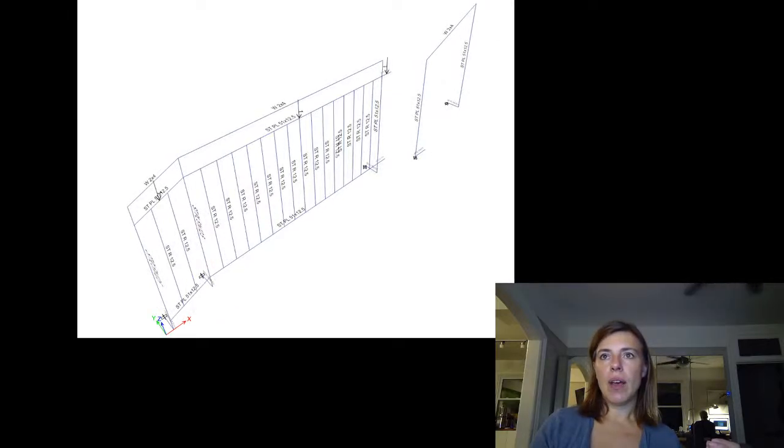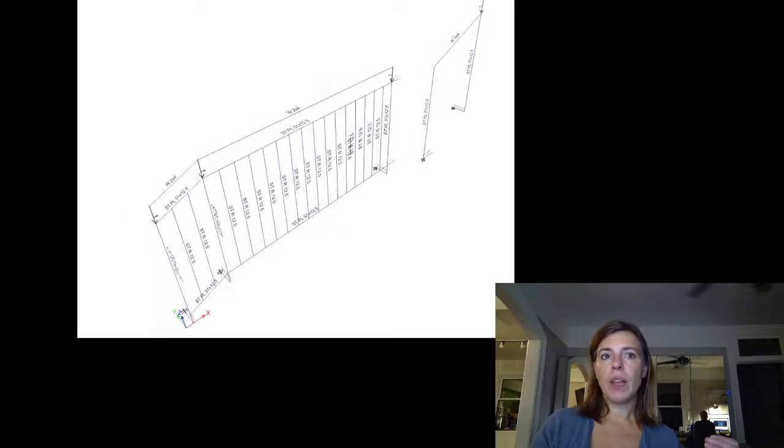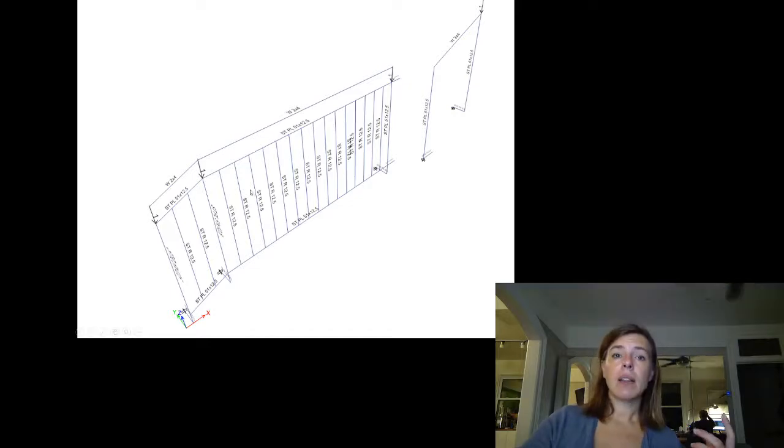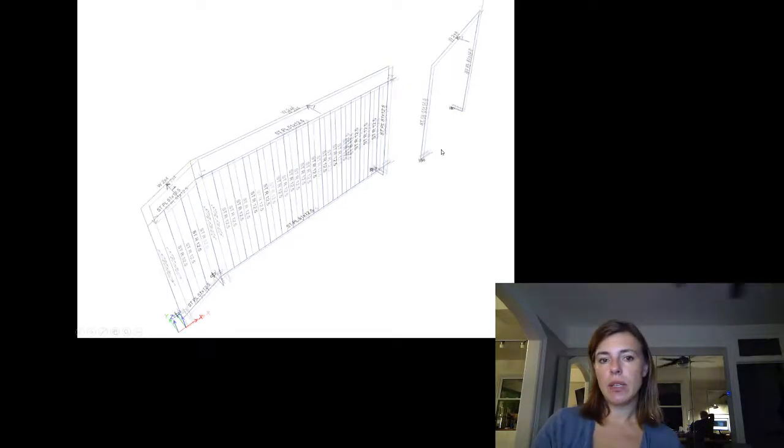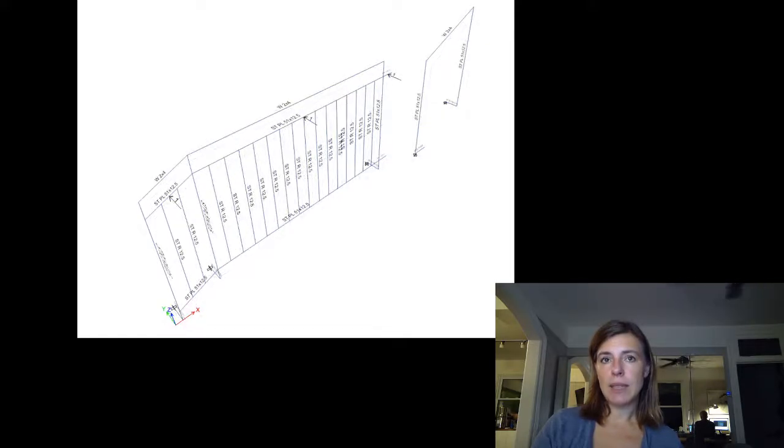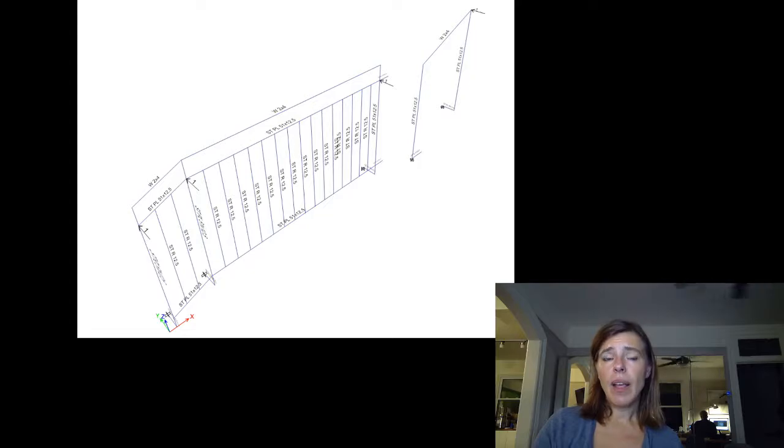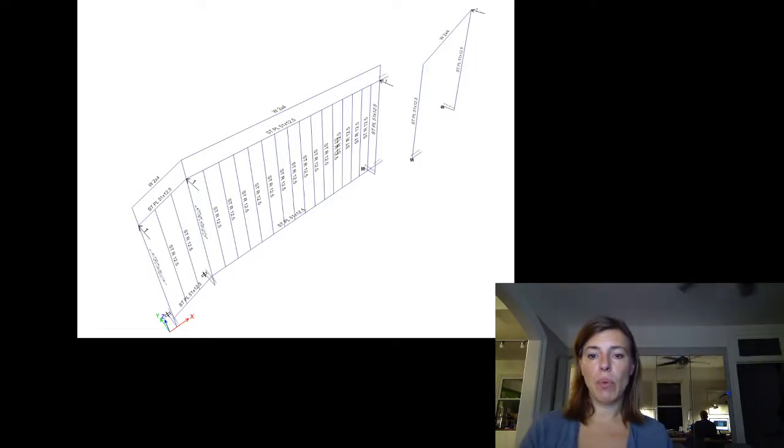Same for the top rail. And then I wanted to check my post conditions because this is where I was going to pull out my reactions, and I wanted to see how these reaction loads would be impacted by that and the buckling capacity of these posts. I wanted to check the top rails in bending, weak axis bending, and the posts for a 1 kilonewton point load.